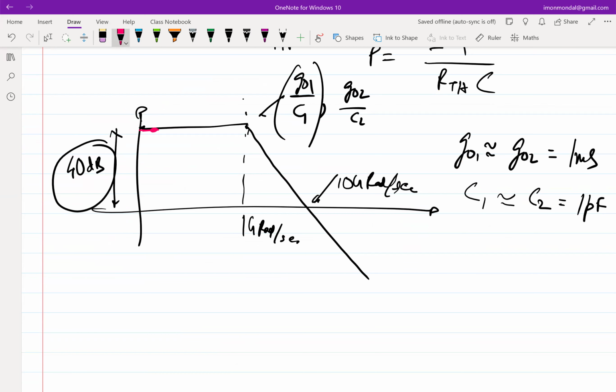It essentially means that now it will have a 20 dB per decade roll-off. And after it hits the second pole, it is going to have a 40 dB per decade roll-off, right? So you see, this is slightly better. The way I have drawn it, it is slightly better because the poles are far apart, but still the UGB falls after the second pole, right? So if you do this analysis and find that UGB falls after the second pole, then you probably have to increase the value of capacitance even further.